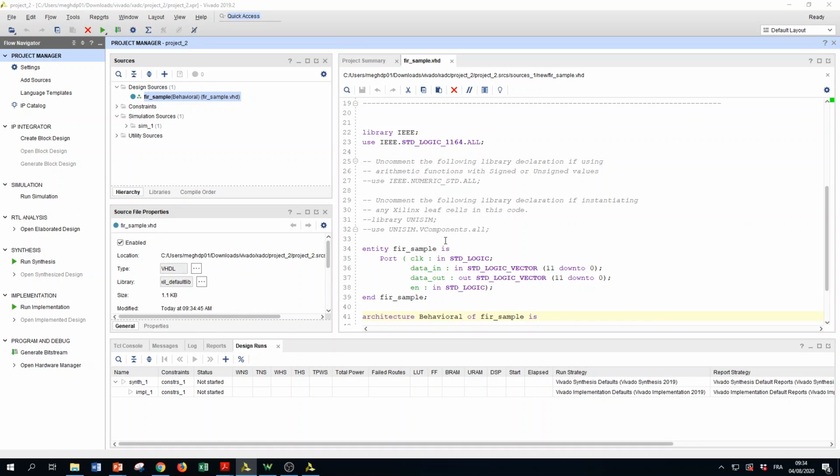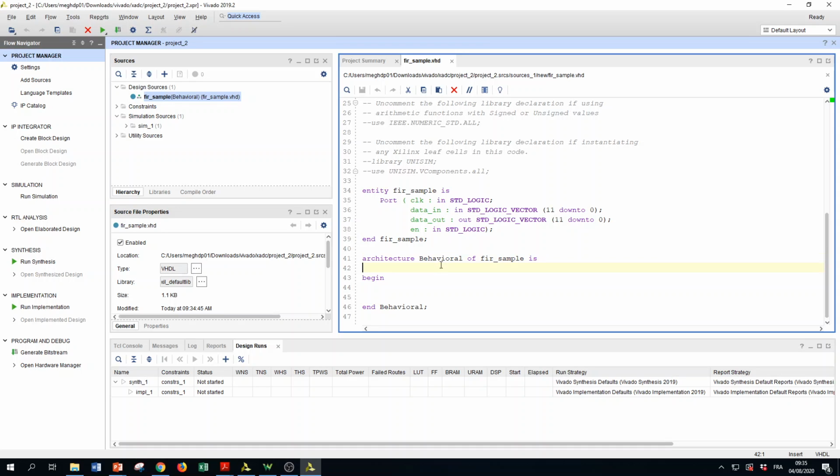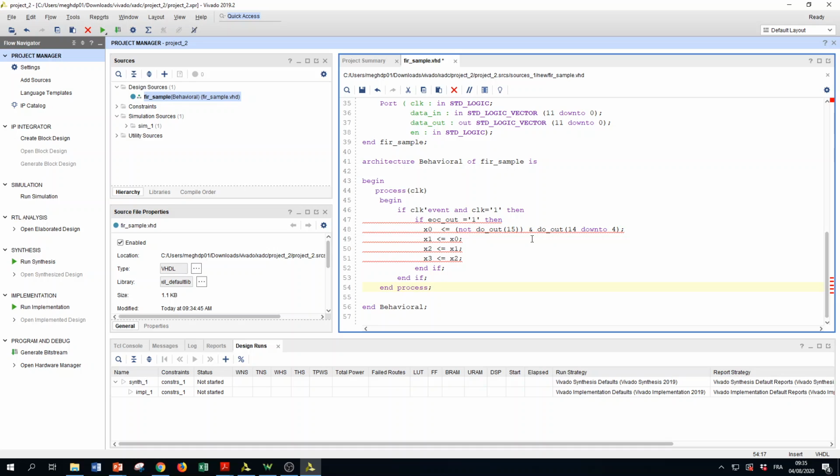And here I just do a moving average, so of size maybe 8. So what I will do is to create a shift register for the data, for the X. I have already done something for 4, and then I will do it for 8. So here is a process that creates a shift register for the X, so the delay line for the input signal.